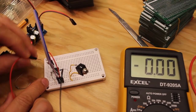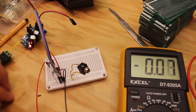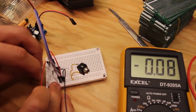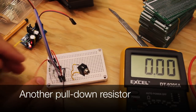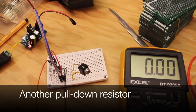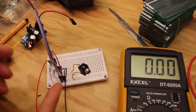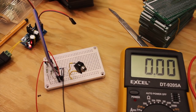But because we add a diode here, the output signal is kind of 0. It is not exactly 0, and that is why we add this extra 100k resistor to ground, and now we get absolute 0.